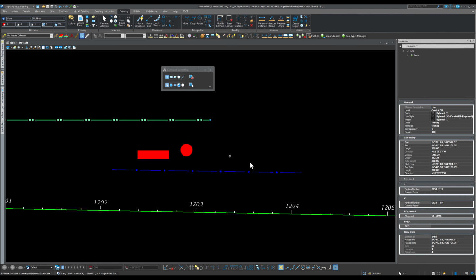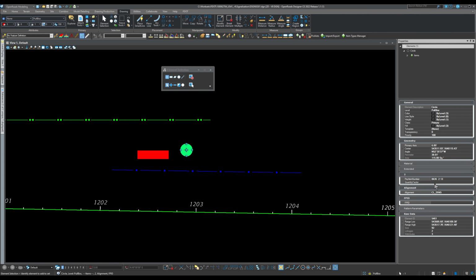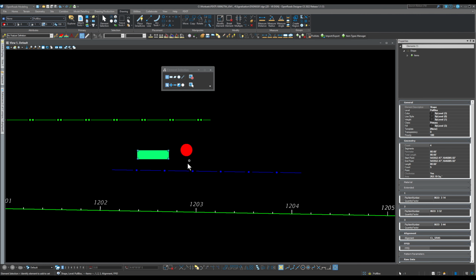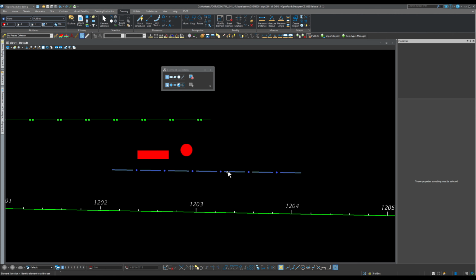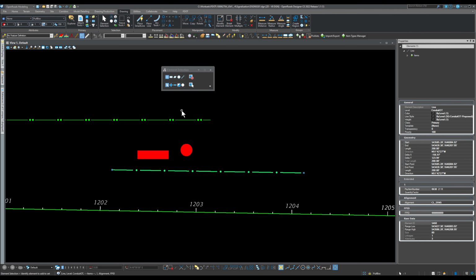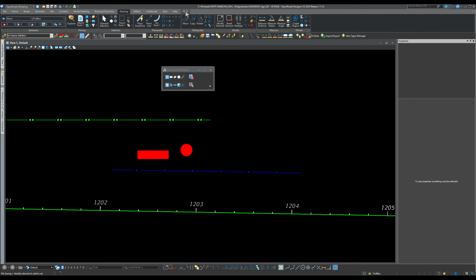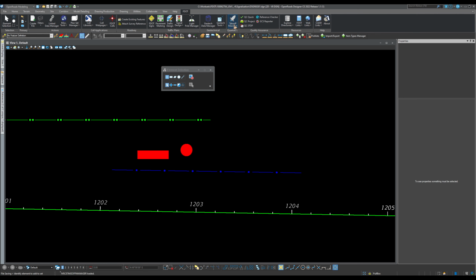So all of them now have numbers and alignment, but no FPID. If I select one of them and I want it to be FPID, takeoff manager is gonna spit out different Excels. These are supposed to appear in the same Excel, but because I picked the FPID number, it's gonna give me a separate Excel for it. So pay attention to that. So let's just run takeoff manager now and see what's gonna happen.